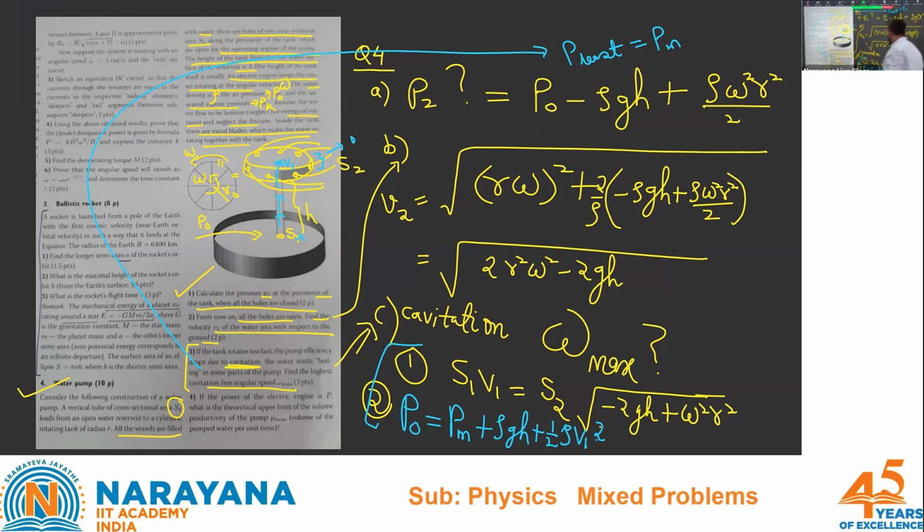So basically what you need to do, from these two equations, solve for PM, that is P least, and ensure that this becomes equal to P saturation vapor pressure. So if this becomes Pk, exactly at that moment, it will start boiling. The cavitation process will start. So your omega should at least be this much, but should not be higher than a certain value. You're getting my point?